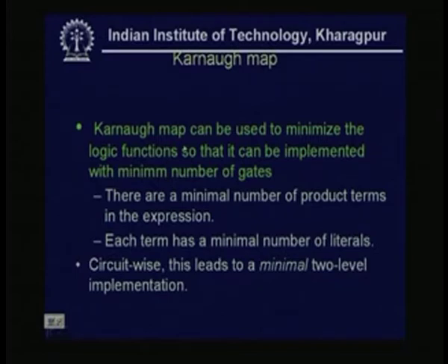So, the Karnaugh map can be used to minimize logic functions, so that they can be implemented with a minimum number of gates. We will see that it is a graphical representation of Boolean expressions if they are in some standard form, either a sum of min terms or a product of max terms, because a product of max terms can always be represented by a sum of min terms.